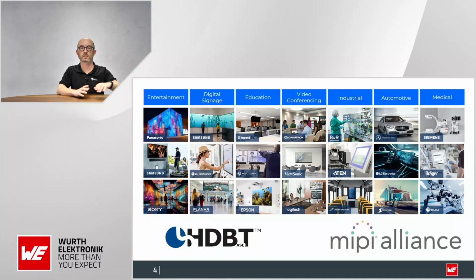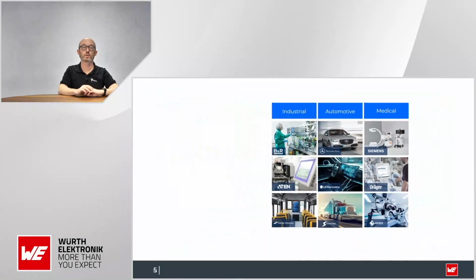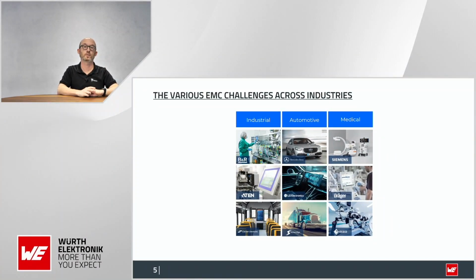As a second industry standard, we are contributing to the MIPI Alliance physical layer A-PHY, which is also a serializer, deserializer combination for transmitting video data from optical sensors, radars, and lidars. I will focus on these three industries today and show you various EMC challenges across them.